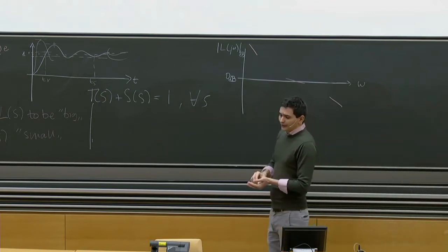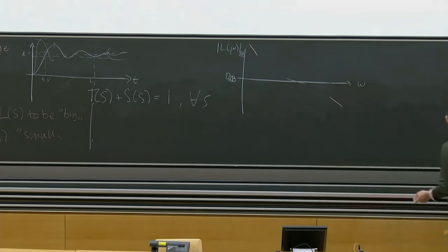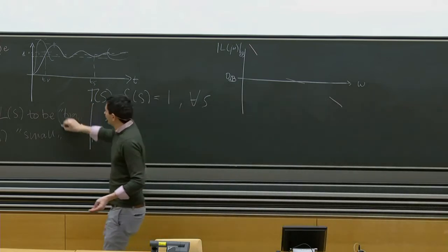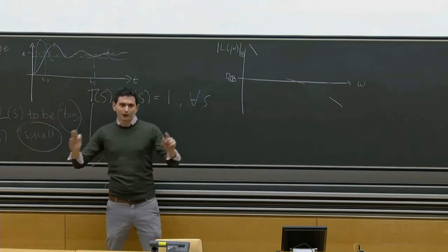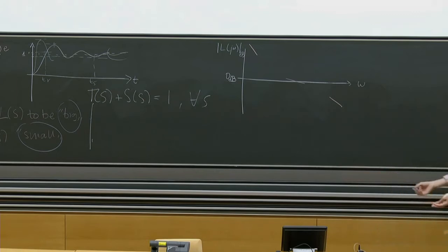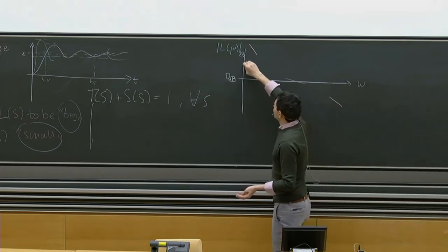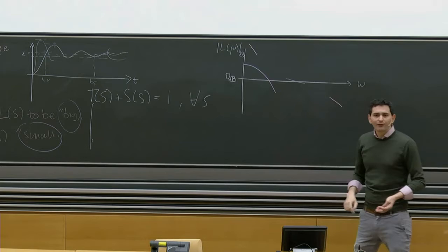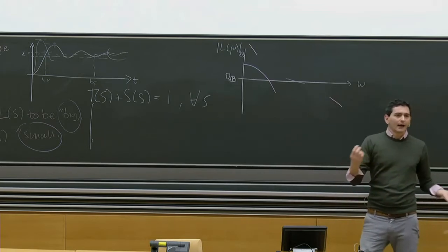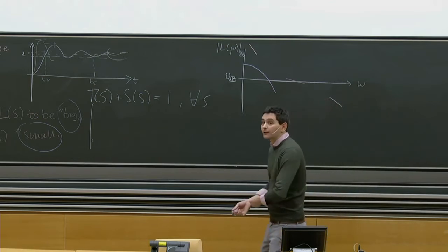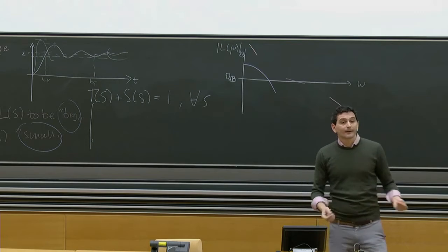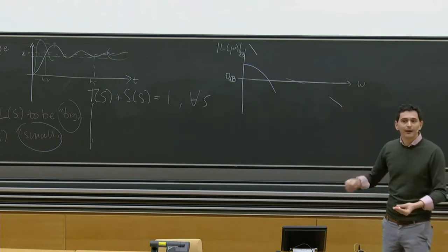So typically, we saw that the way this is written is by saying, let's represent this big and small, which we put in quotes because big and small don't really mean anything if not compared to something, right? So typically one defines the specifications in the form of, we would like the tracking error to be at most 5%, 1%, n% for signals up to 1 hertz or 10 hertz or whatever it is, right?